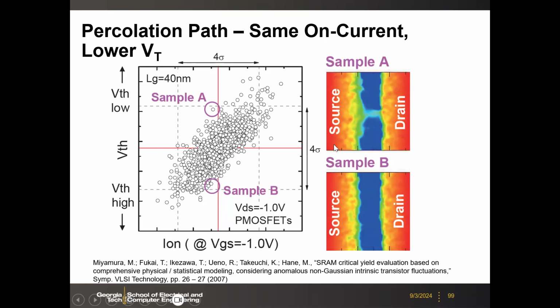Of course, this is bound by TCAD simulation. So you can correlate this data point with this kind of potential or current, depending on the dopant location. You may have dopant here, here, here, but not here. Therefore, you will have a leakage path. You have a low VTH compared to this one, where you can cut off across the entire channel.